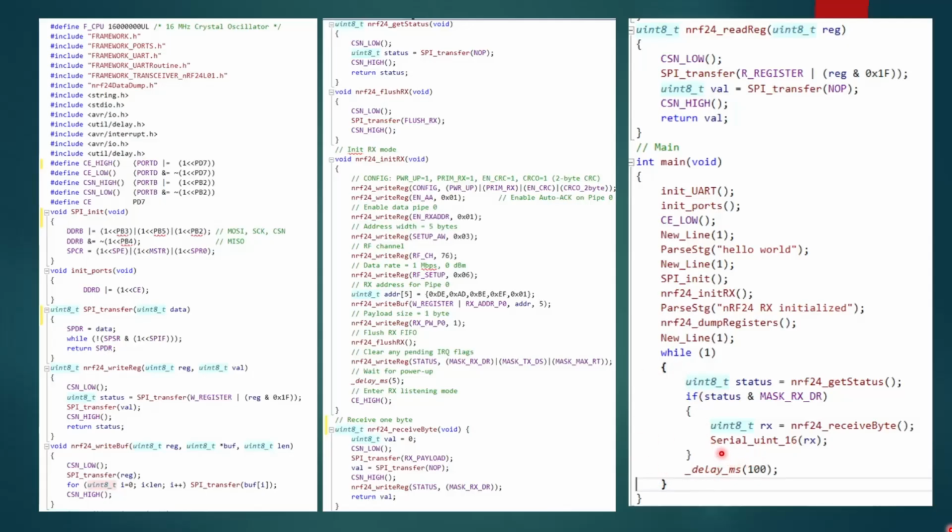Now, one of the things I do here, once I get into my while loop, is I try to use the minimum amount of communication through the UART with the laptop, because all those things create interference, and that could pretty much be the reason your messages don't arrive, because of the interference created by your communication to your serial.